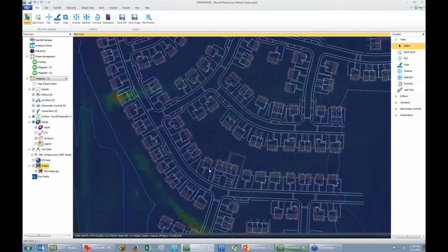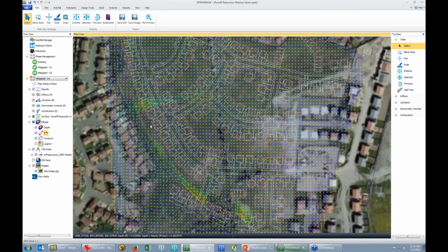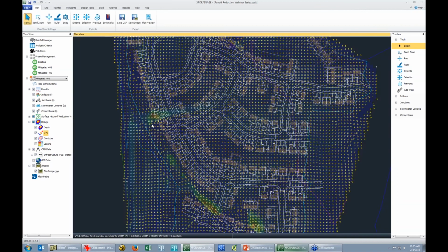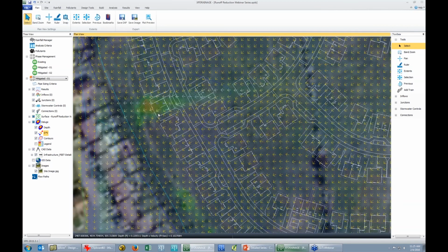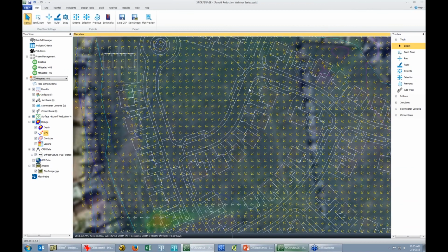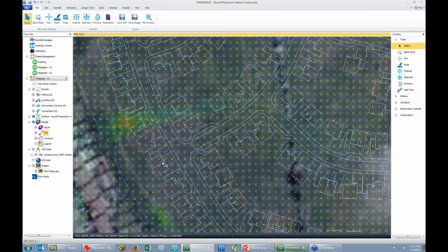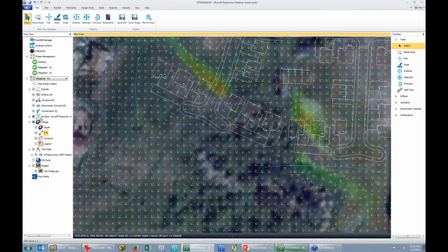Now there's also this large collection zone we need to bring in. We need to kind of route this flow down maybe to a pond for the really high volume treatment mitigation. So perhaps this would be a good location for a swale down one part of our site. Again, if I turn on the vectors, you can really see how this flow is going to move from this northeastern portion down across the site, graded so that the streets will capture the flow, and we can route that down here to the southernmost portion of our site.